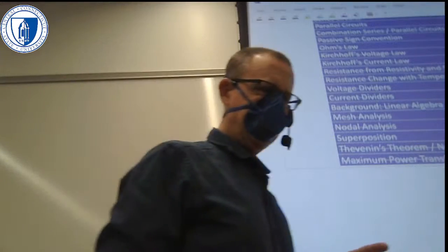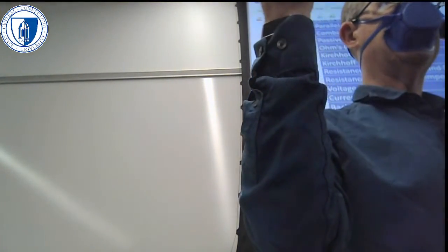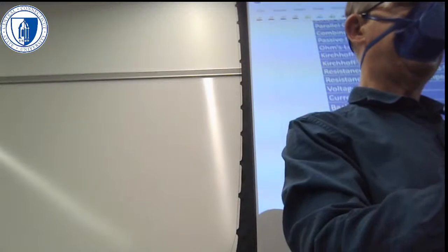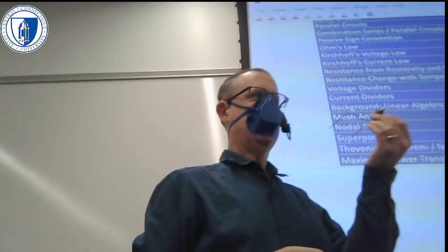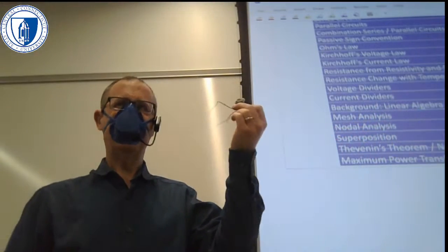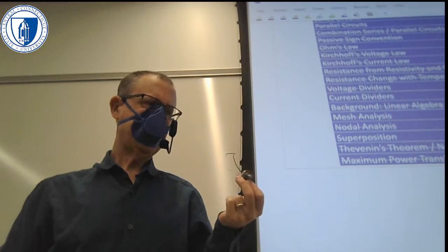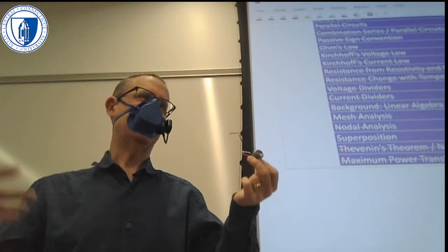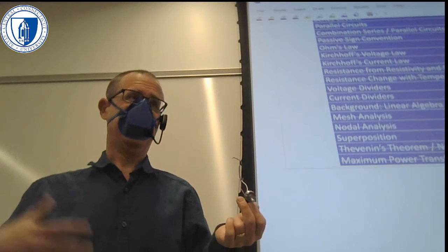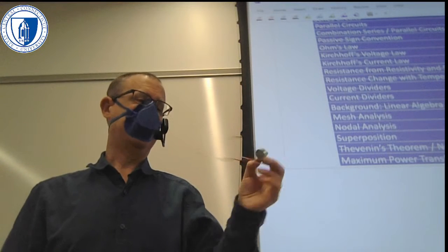The other problem I noticed last night is the lab says that these are 10K potentiometers. They're not all 10K potentiometers. Some of them are 1K potentiometers. If you get a 1K potentiometer, I don't want you to use 1K as the value of the resistance. I want you to use something less than 1K, say 150 ohm or 270 ohm, something like that.